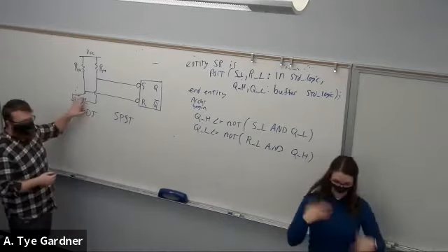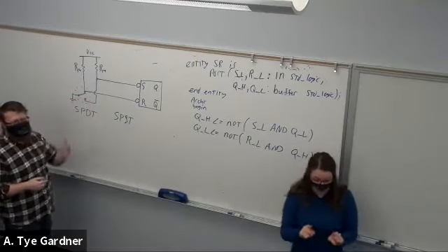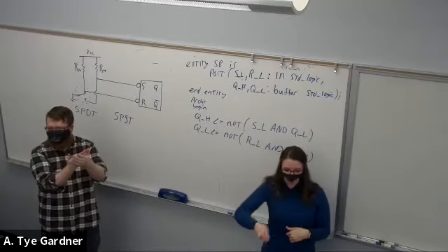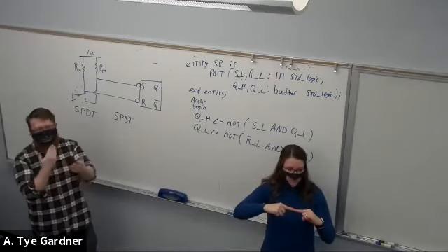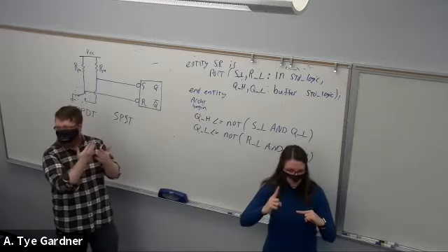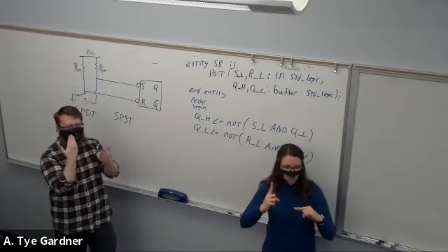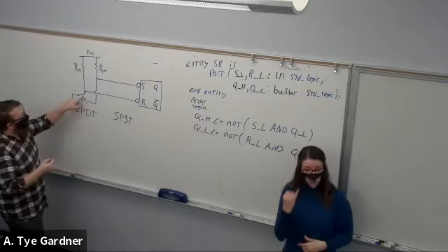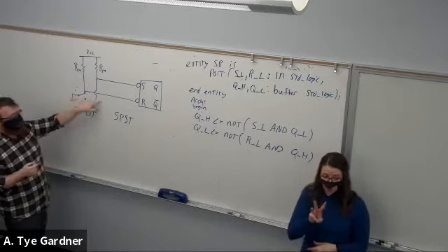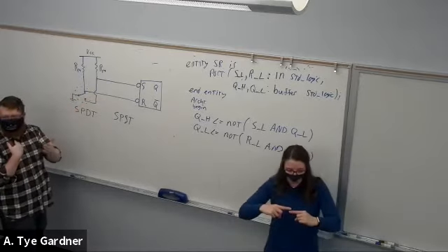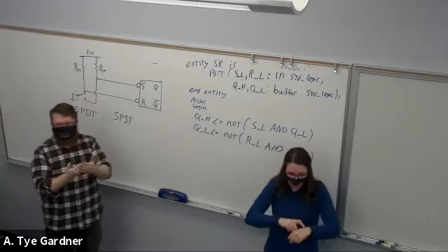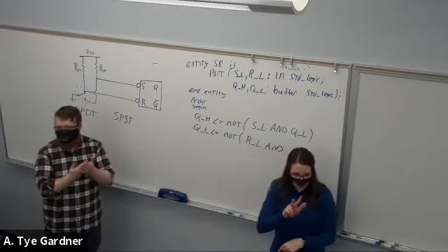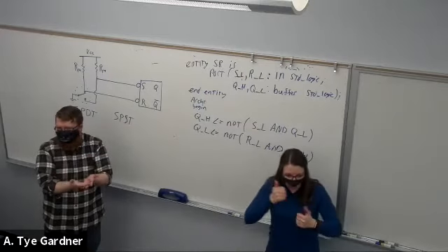But we've got this little switch, and we'd like to imagine that we throw the switch and it goes closed, right? But it doesn't. What happens is it hits and rebounds. And so it goes bum, bum, bum, bum, bum. Right? It bounces. So if I were to throw just a regular switch into here and it was counting the number of times the 1 or 0 changed, it would go 1, 2, 3, 4, 5, 6. Right? Every time it bounced would be a new output.